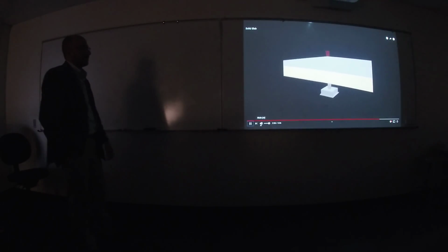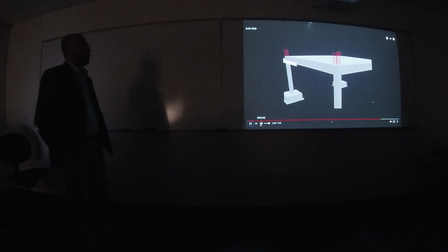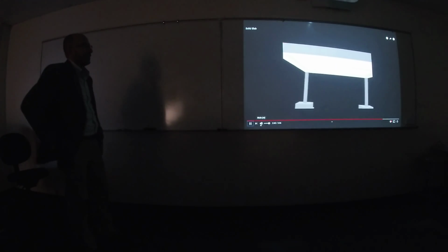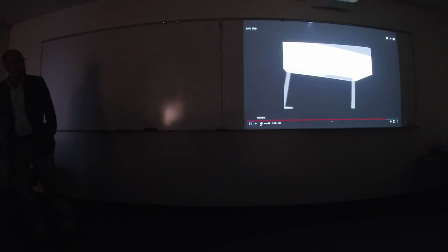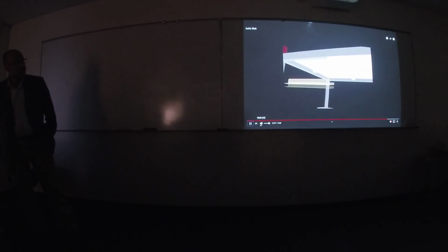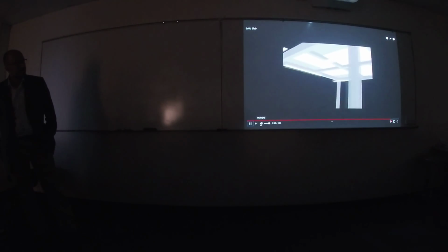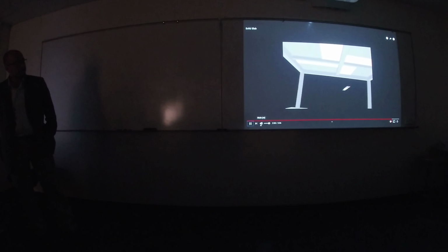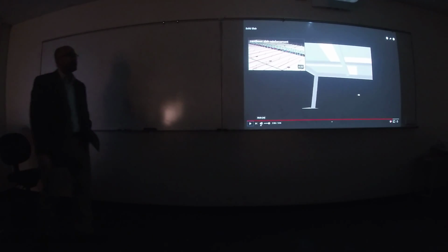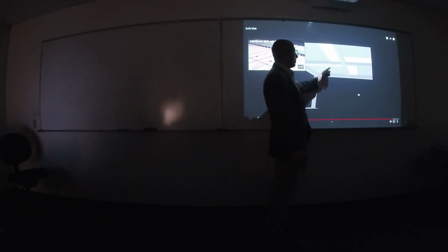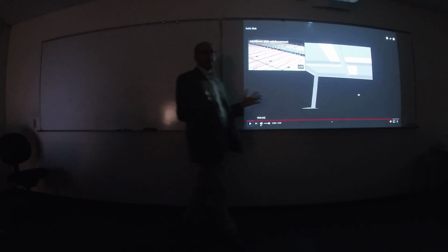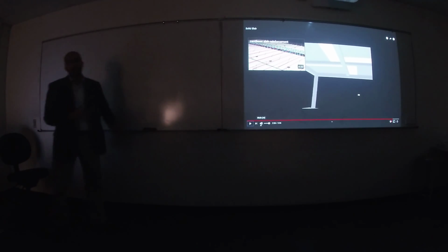Pouring concrete. Remove your formwork. Here is the final shape of your solid slab from the bottom. You have slab, you have drop beams supported by columns. You got it? What is the meaning of solid slab?